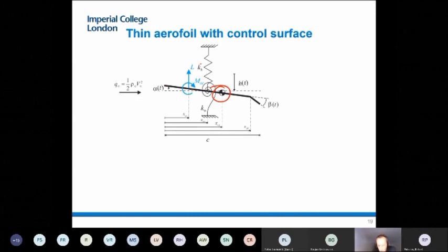And that mass will go around a center of gravity, which I'm going to position somewhere else on the airfoil. So in dynamic aeroelasticity, I will always need to deal with first identification of aerodynamic effects, lift and moment. Again, these will be forces which apply at a particular location of the airfoil as resultant forces. I will need to deal with elastic effects, the torsional springs, K_h and K_alpha, which again will be applied at a second location, x_EA, I put that notation there.